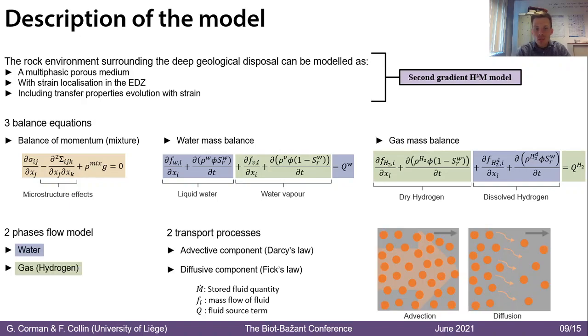In addition, the model incorporates the features of the two-phase flow transfer approach, in which the fluid mass flow is made of an advective component of each phase according to Darcy's law, and a diffusive component within each phase according to Fick's law.